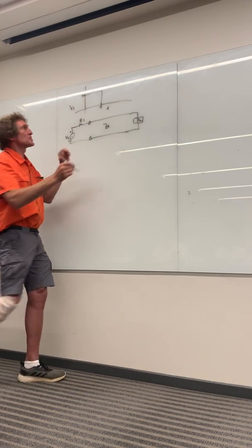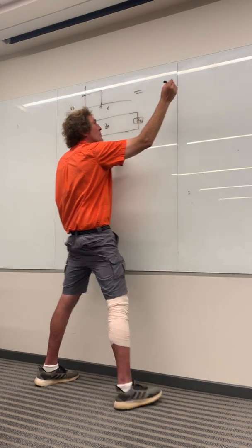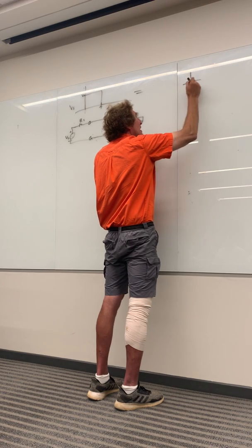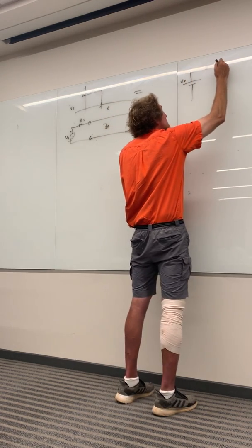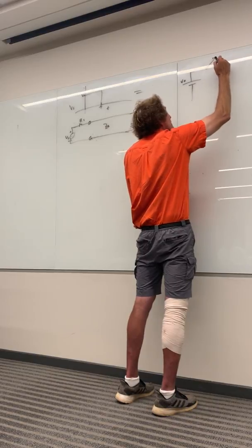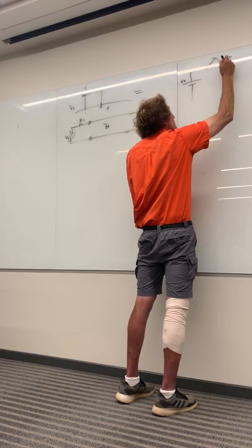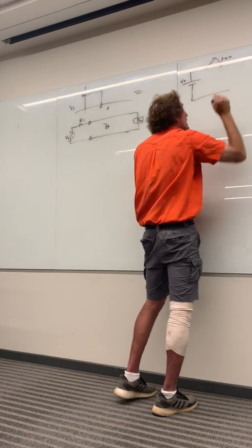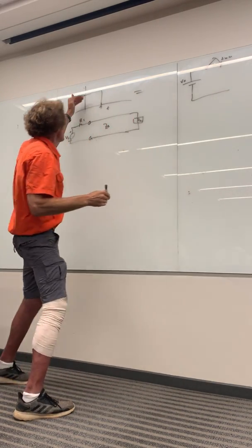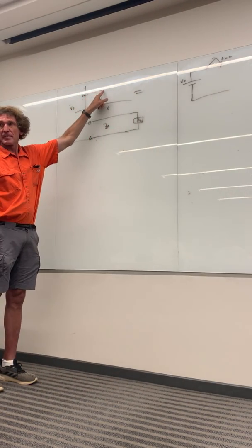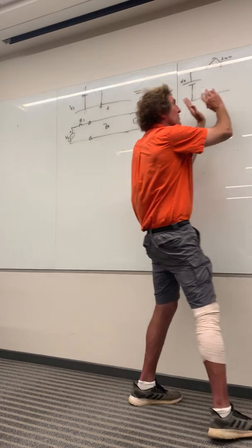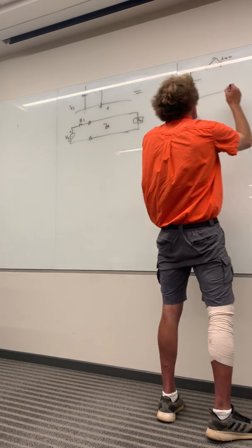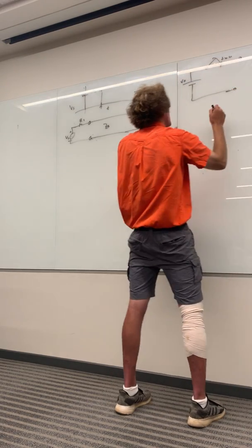We say this pulse right here can be rendered like this. If I have a battery of V naught here, and I have a switch right here that turns down at t equals 0, right? And that would start it, correct? Then what I want to do is this. I'm going to find the voltage on the transmission line for this source. And then I'm going to add to this.